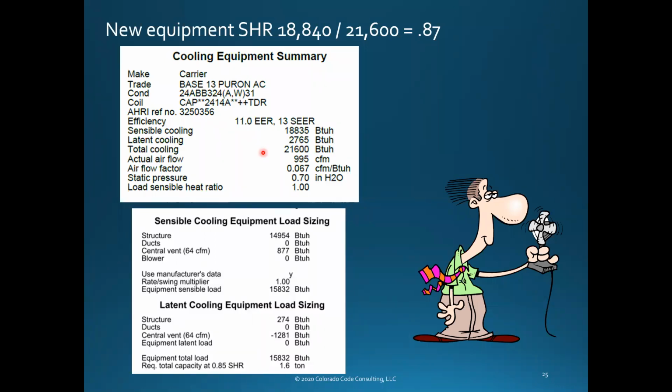Many times, most designers don't monkey with this. They don't know enough to do it. They'll just pop in what the manufacturer's AHRI data is, and they don't manipulate it, which is why it's important to get the expanded performance data so that you can actually see what it really does. And hopefully they've got enough wherewithal to actually change the numbers within the software, so you don't have to do the math for yourself. Good questions. Those were good.